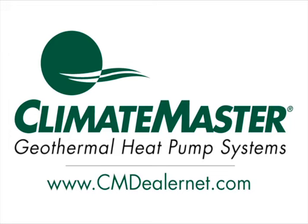You're going to have a unit that trips out. So having done a couple of those, I never did put in an expansion tank, but up in the Seattle area, well, I wasn't dealing with a lot of cooling temperature, which is expansion. So I probably wouldn't, but it doesn't mean you absolutely cannot. You just got to make sure you use a very good one. If I was going to put one in, it would probably be the domestic hot water one. It's got a better bladder, a little bit better pressure rating. But heavens, if you buy the unit with the internal pump, it's got an expansion tank already built in.